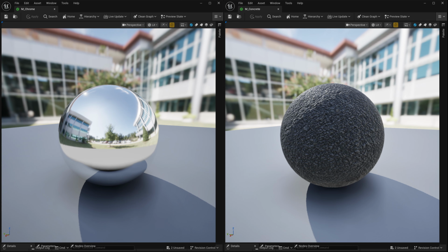Now, one thing to keep in mind with the PBR workflow is we also have controls like metalness or metallic. So in Unreal, we have a metalness control to determine whether a surface is a metal or a non-metal. And this changes the way your diffuse color, base color gets used as well. When a surface is a metal in the PBR workflow, generally the base color becomes your reflection tint. So if you're making gold or something, you would change your base color to be slightly tinted more yellowy, orangey, to tint the reflection of that surface. And that's a big difference.